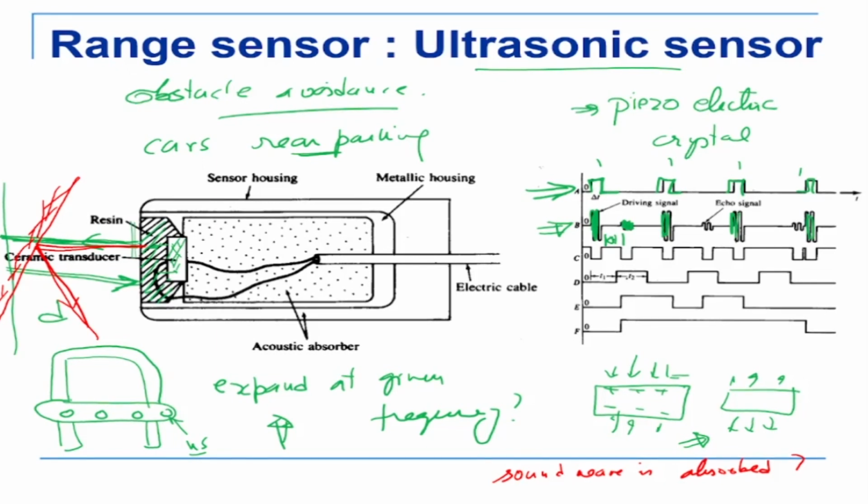Okay. So what we do in a mobile robot is, if this is a mobile robot, the top view, and these are the wheels, we put ultrasonic sensors normally all around the robot like that. Okay, or we have an ultrasonic sensor which will scan, so it will move. So first it will move to this side. Okay, so it will move this side and it'll move the other side. First you'll see this side, this side, this side, this side, this side. So we mount the sensor on maybe a servo motor, and the motor will rotate so that it can see all sides. And then if there is an obstacle in front, okay, or wherever the obstacle is, it can figure it out.